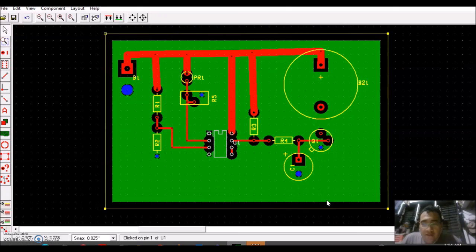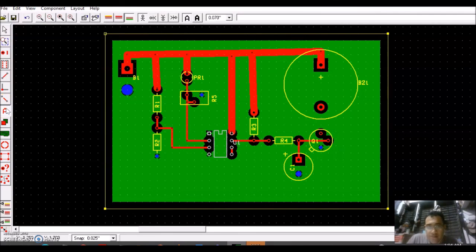And then finally, for your own circuit, add your own initials in an unused corner of the chip. Do the initials in the top metal red layer rather than the silk screen layer, because if we use mini boards, the silk screen layer is not included. To add text, click the text tool, and then do the initials on the top copper layer.